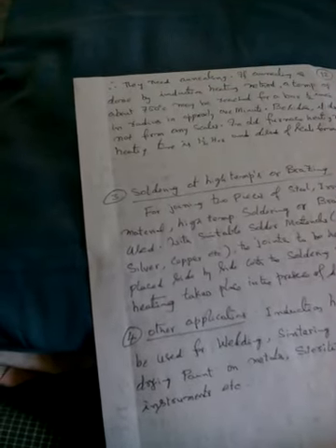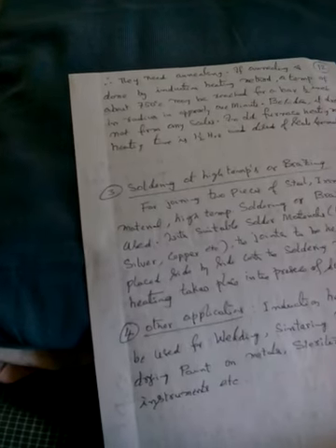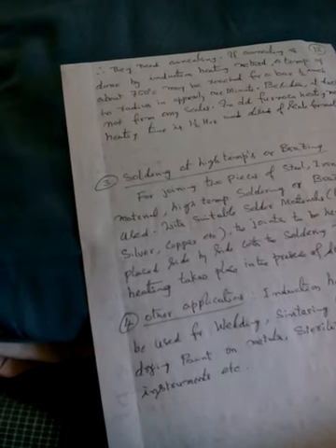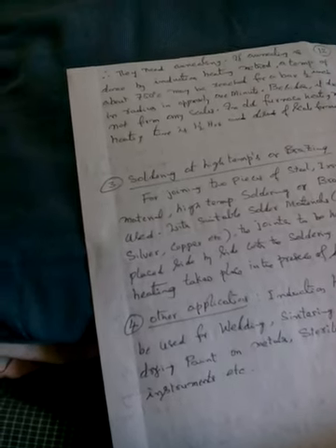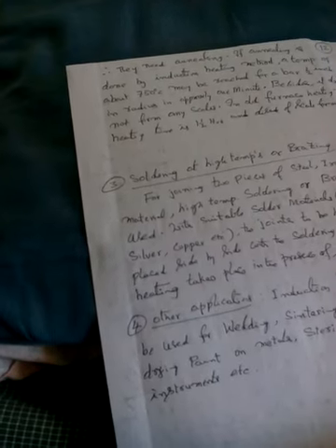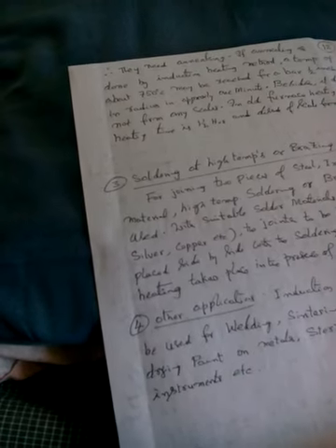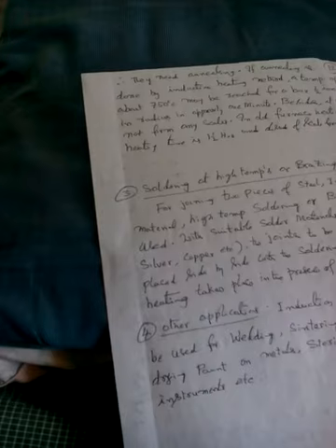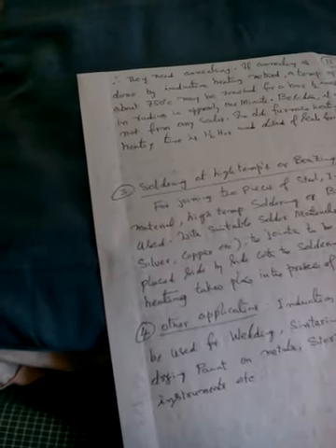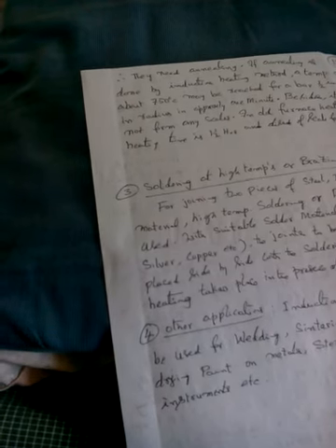Okay? So that can be avoided here. We can reach 750 degrees centigrade within 1 minute. That is what you call annealing. Annealing can be done very economically, very fastly. So large number of rods or vessels can be annealed using induction heating method. It is very fast and also very efficient, okay, compared to old furnace method.